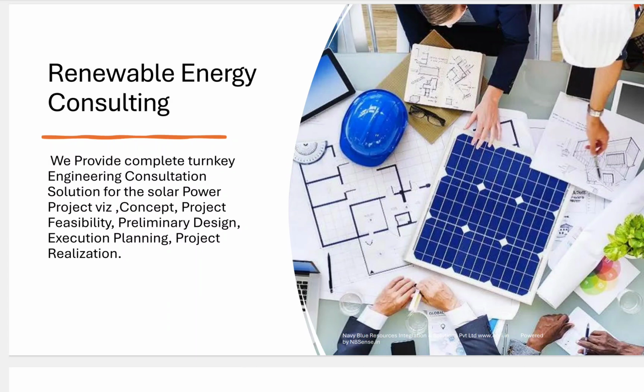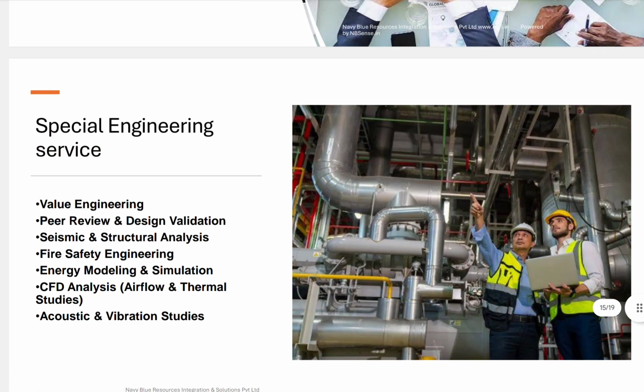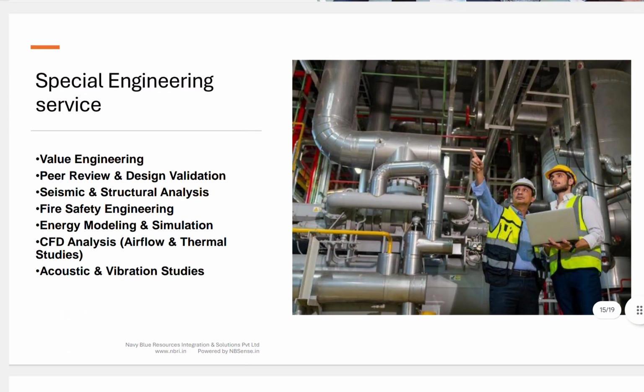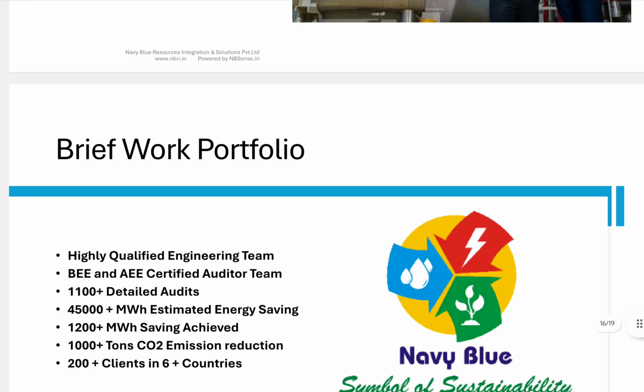So there is some testing. Thermography we are doing by drone; we have drone thermography. We have to check the plant level performance, then the individual inverter level performance, then the string level performance, then the module level performance. That type of detailed analysis we need to do in solar consulting. So that we are doing. Correct? The specialist engineering services, which are not listed in this category, but suppose somebody wants a very special engineering service, then we can give that as well.